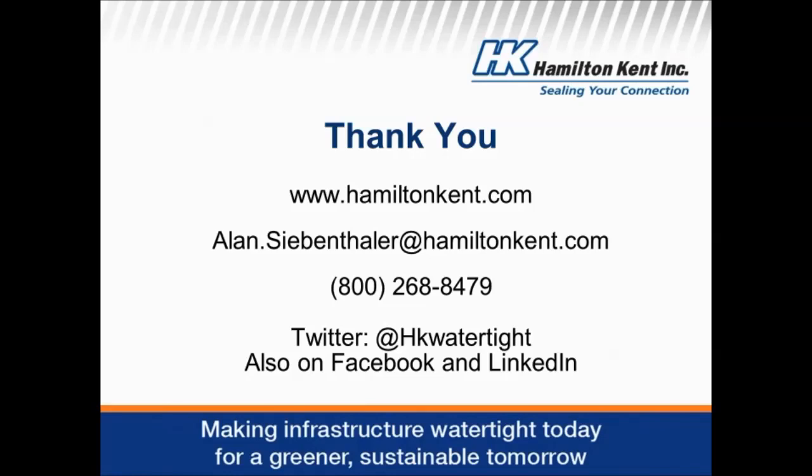Okay, well, one question that came through is size of connectors, and I think I kind of covered this briefly. For the mechanically installed connectors, there are some companies that manufacture boot connectors up to very large types of pipes, but then others, like Hamilton Kent, we only go up to a smaller size, just because we think cast-in connectors are a much better product for large pipe.